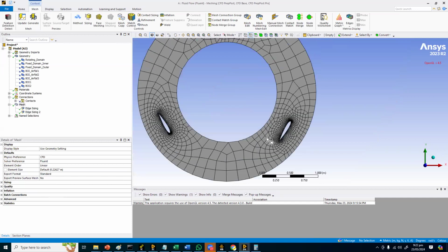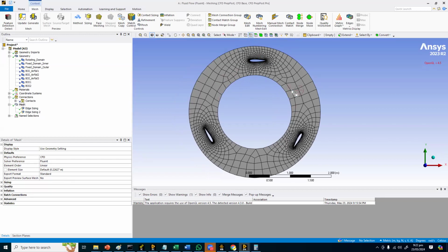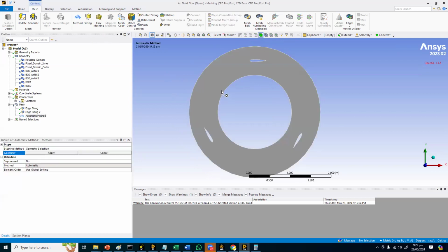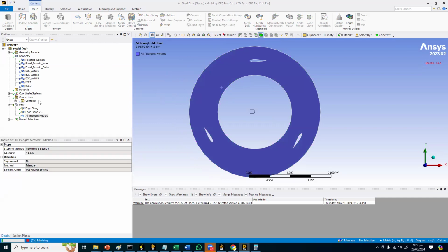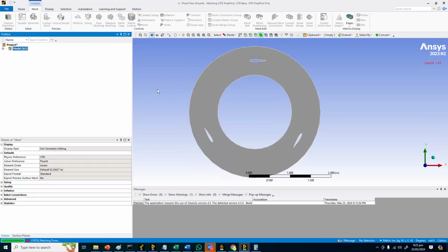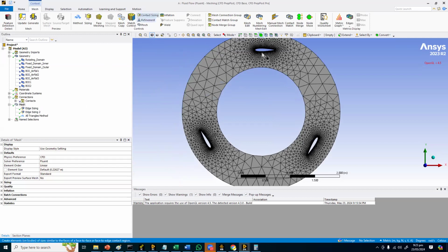We should also be putting the meshing method here. For that meshing method, we can work with this type of hexa meshing, this is the pave hexa, or we can also go with tetra meshing. It's your choice. So let's make the method tetra meshing. Make the selection as a single select, and I will be using the triangles and click on generate. Like this.